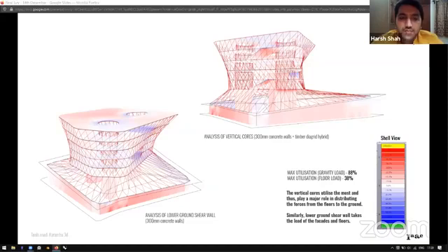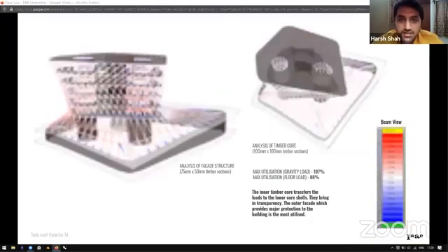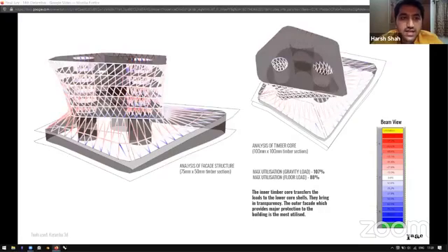Then we looked into the beam elements in further focus on the facade, like the diagonal timber beam elements on the facade, as well as the light wells, where we saw that they worked much harder to support the overall structure due to basically the vertical loadings. So these studies help us to understand the effectiveness of the timber concrete hybrid over the predominantly concrete structure.